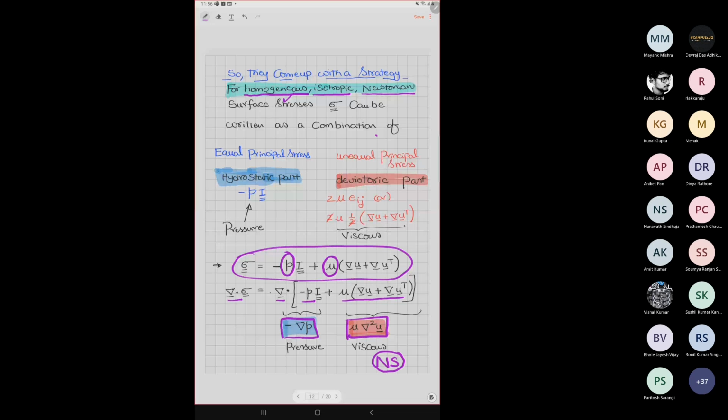At this point, don't worry about each and every micro detail, but just have a generalized overall theme. You have finer size materials, surfaces, and stresses acting on that. Different surfaces, different stress components. If I carefully balance all these combinations, I will write Newton's second law of motion on the tiny element: D by dt of rho u is equal to divergence of stress plus external body forces.